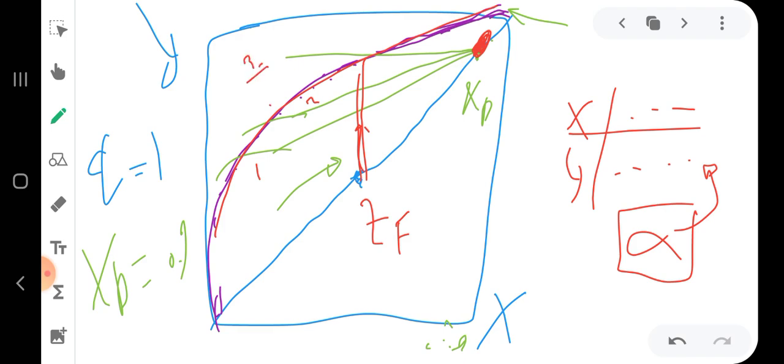As we can see, it is the third line. So this line intersects the equilibrium curve and the Q line at this point. So this will be the line that I'm going to use to determine the R minimum.